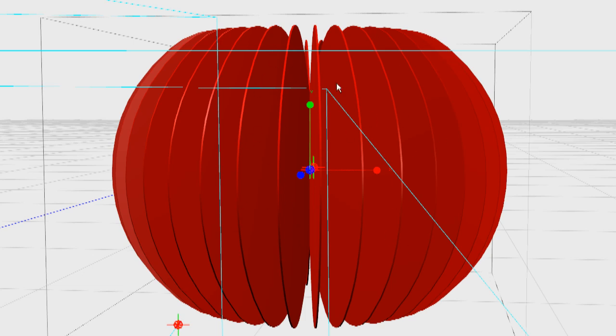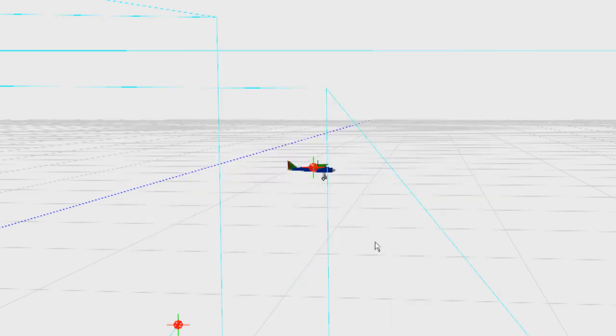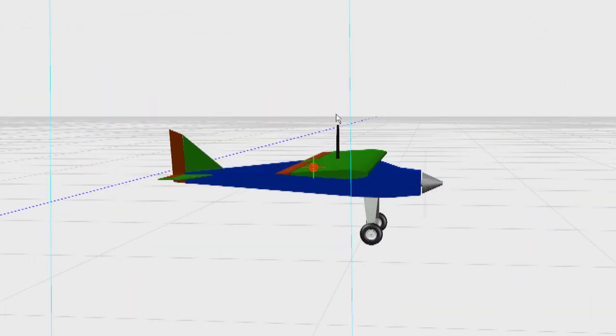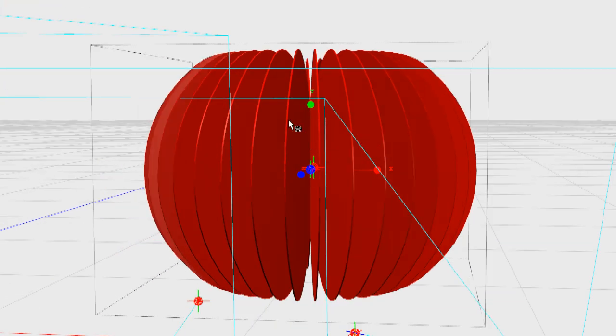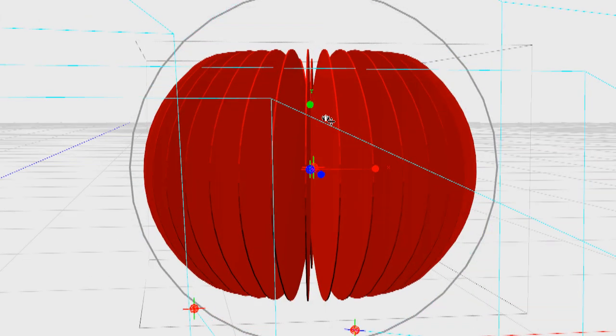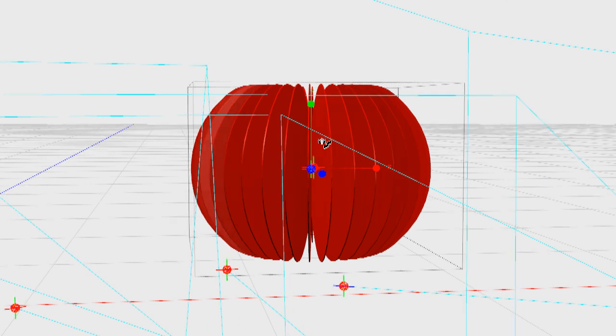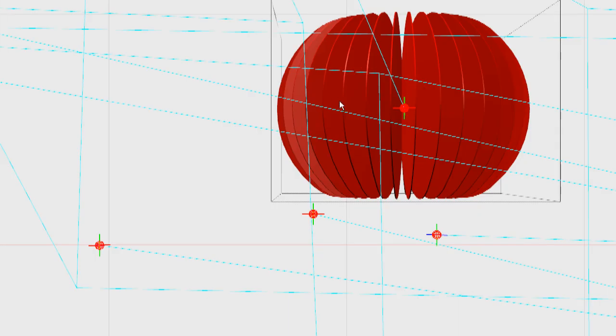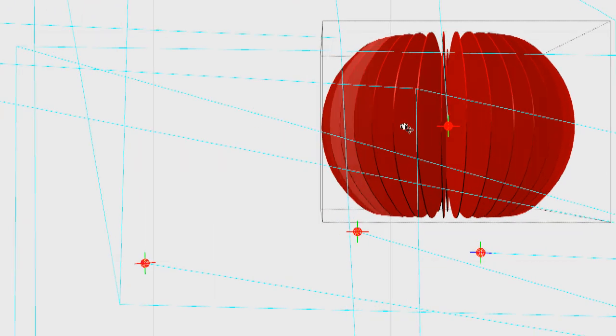Now you'll notice that these sections are oriented vertically. This antenna is a linearly polarized antenna. It's linear polarization, which means it's either vertically or horizontally polarized. That is controlled based on how we've mounted it. Because we're mounting it in a vertical orientation, we therefore have a vertical polarization pattern from the transmission. So this is our plane, and obviously we have the same antenna on the ground station. I'll switch to the front view, which is actually the side, but we'll call it the front.